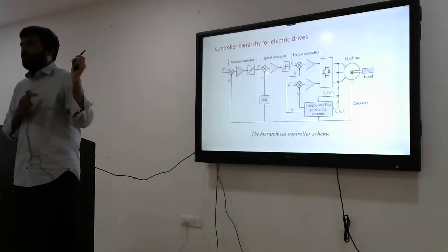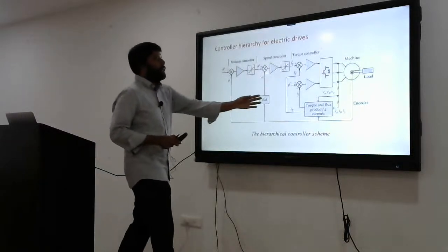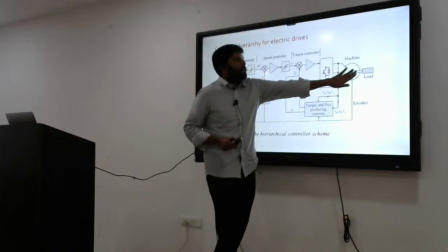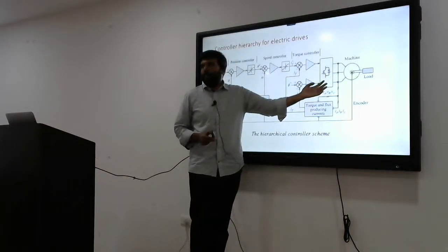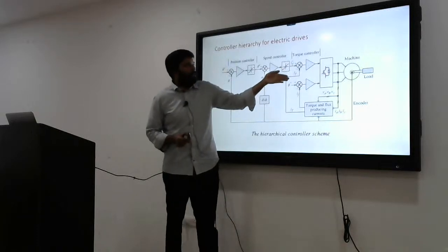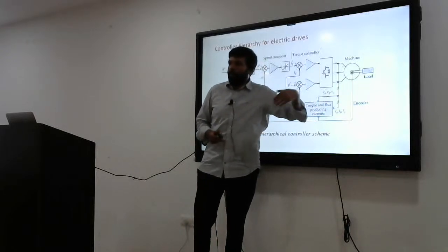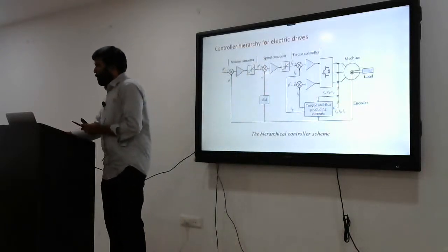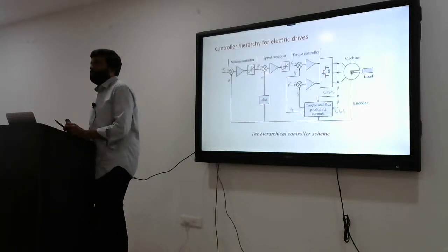Here the inherent motor characteristic is coming under your control. This is the actual system, this is the control system, this is the control mechanism, this is the power semiconductor element. By taking a combination of power semiconductor element and control logic, we can change the motor characteristics based on the load requirement. So that's why this is called the universal block diagram. This block diagram is common for all electrical drives: robotic application, satellite application, electric vehicle application, right?